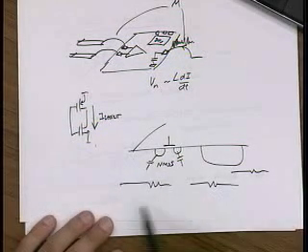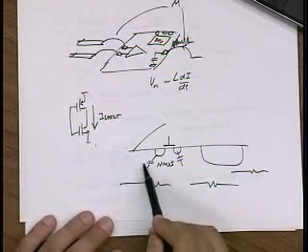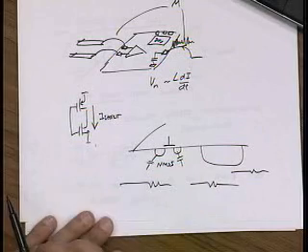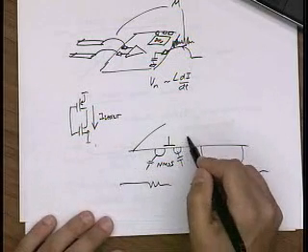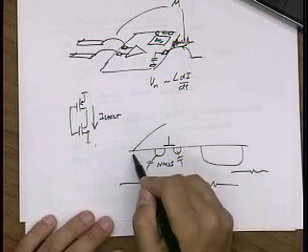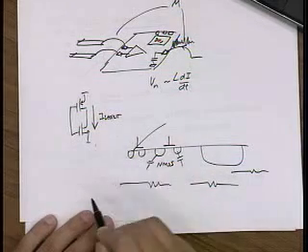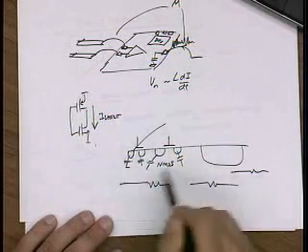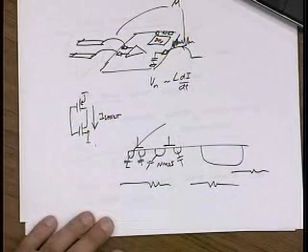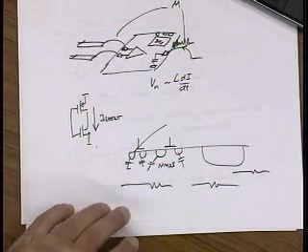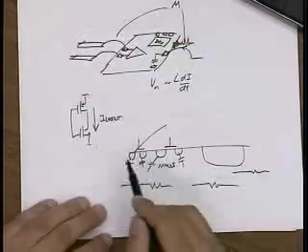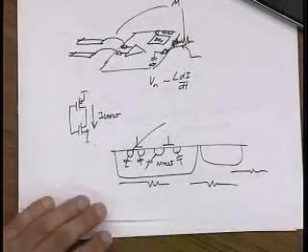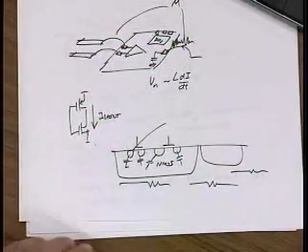So there's lots of noise currents flowing in here and coupling into our circuits. The good thing is that if I have two transistors which are close together, then their noise pickup will be roughly the same, and so a differential circuit will reject this. Obviously, if I had a triple well option, that would help as well to get more isolation.